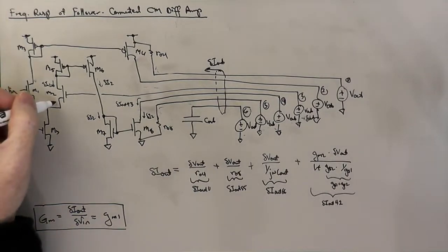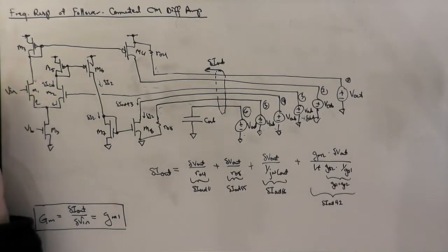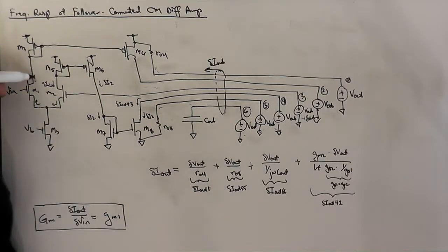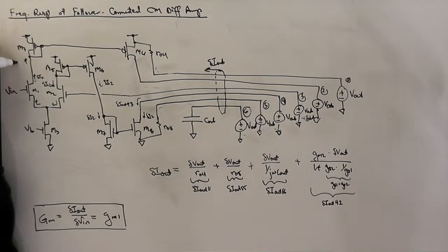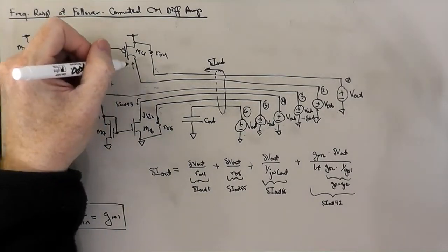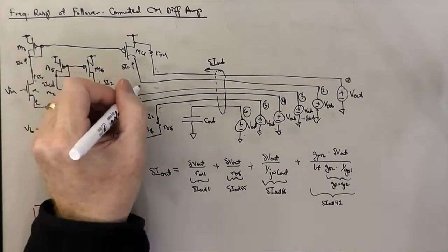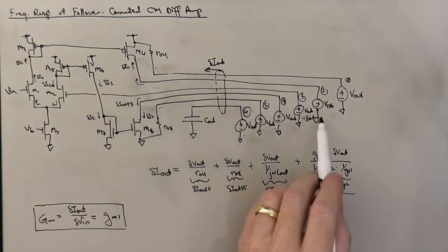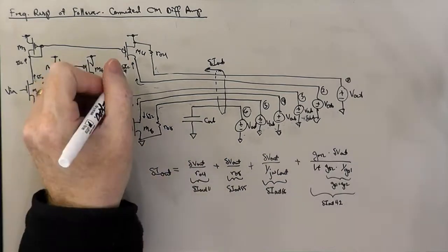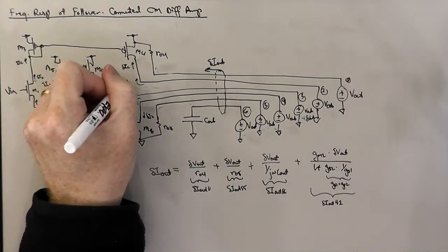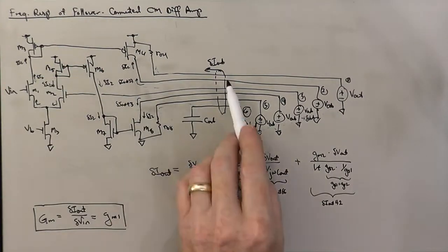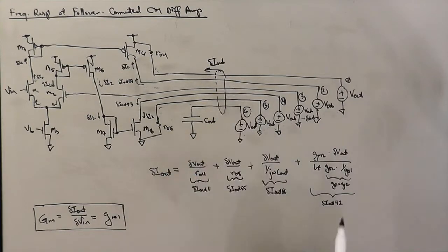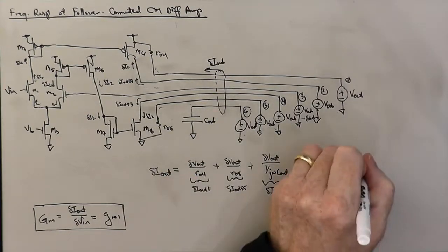Well, the other thing that this delta I2 does is it flows out of the source and back up M1, out the drain of M1, and it's mirrored by M3, M4. And that will represent a delta I out component in branch 2 due to replica source 3. So that's a delta I out 2, 3. And that again is going to have a positive sign because it's being drawn into the circuit, and our delta I out for this R out calculation or Z out calculation is positive flowing in.